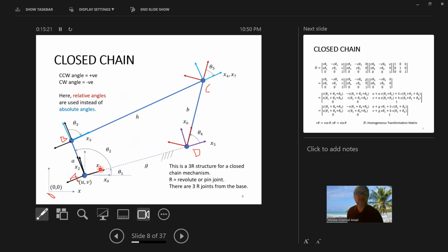So from theta 1, rotate to get to theta 2. This is x1, so by having the next rotation by theta 2, we get this frame to x2. We bring it to x0, then x1, then x2. So x2 is the rotation still at point A. It's not translating yet.